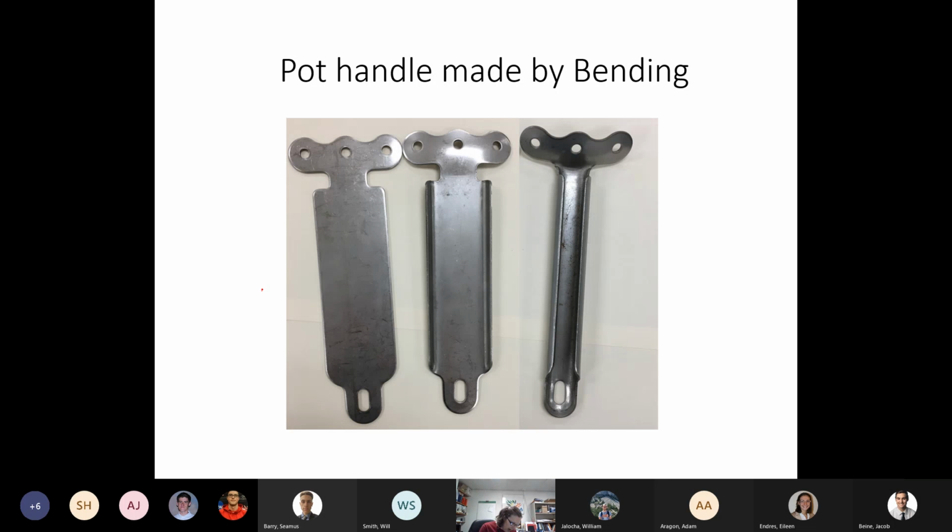So here we would have a blank that has been punched. And we've got the 3 holes and then the hole in the bottom that have been punched. So this has been sheared. We would actually see that sheared edge. So what we see is that we have a bend here and here. We have a bend here, and then we're starting to see these sides are bent again.